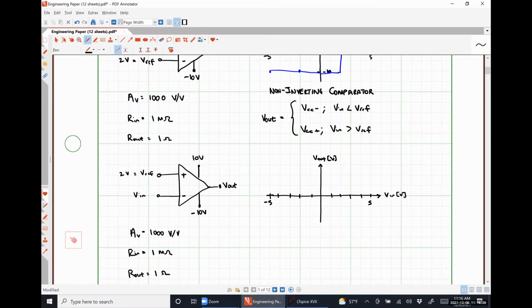All right. So let's walk our way through this thing in a very similar fashion. Let's start with -5 volts for Vn again. So if Vn is -5 volts, somebody who isn't Ian, tell me what our differential voltage is going to be. Sarah, you have any thoughts? So our differential voltage will be the voltage present at the non-inverting terminal, which is 2 volts, minus the voltage present at our inverting input terminal, which in this case is -5. So 2 minus -5 is +7, right?